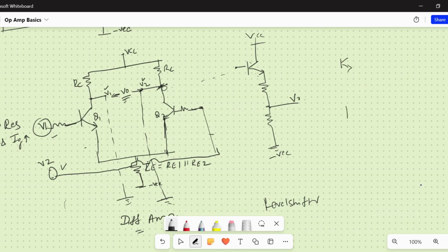It is something like two transistors. One is NPN and one is PNP, which are connected this way. So those inputs are driven by here. So this will drive the load. This has a capacity to drive the load. At the same time, this has a capacity to sink the load current.